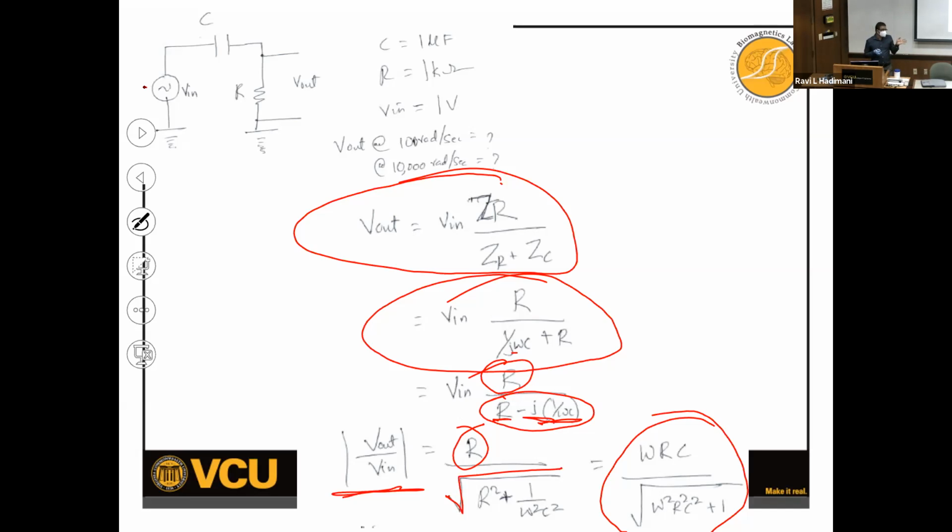Or where you want to block low frequency. There are many applications you can use it in. For example, if you are just looking for high vibrations at larger frequencies in any structural element, then you can use a high pass filter that will only give you output that has signal associated with high vibration. Okay, but you need to convert that mechanical vibration into an electrical signal.